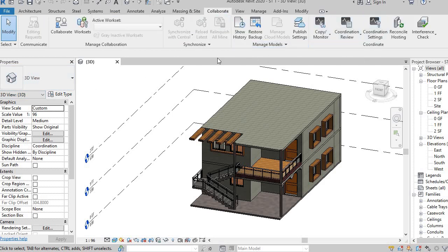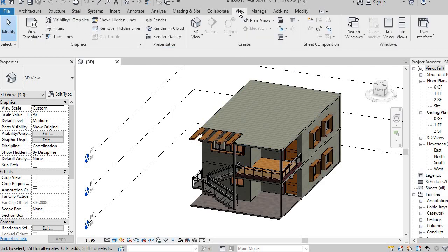This is the collaborate tab where you can add collaborators of your project. Any 2-3 persons can use the same project using the collaborate tab so that you don't need to share the whole file again and again. If you add them as a collaborator, they can access the file without sharing. That's the use of the collaborate tab. This is the view tab. This helps in putting the model on paper. On paper, how it looks with all the dimensions, hidden line, everything can be seen through this tab.